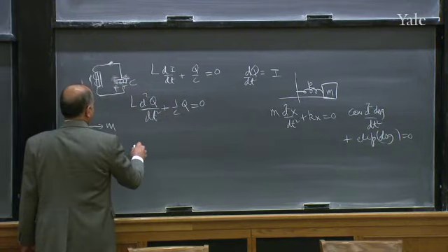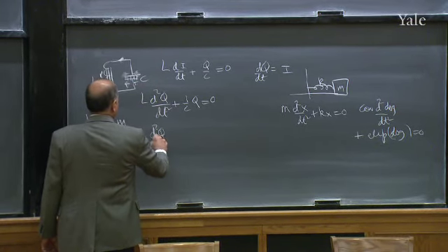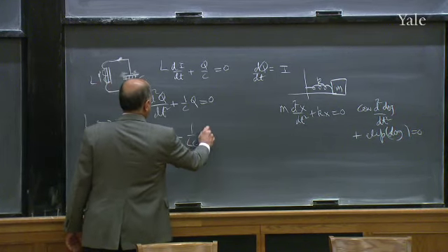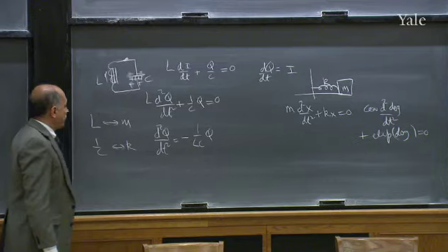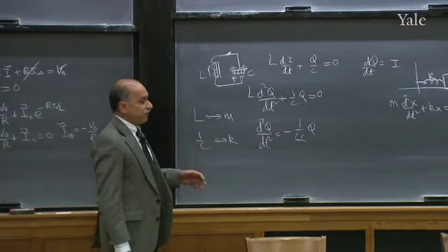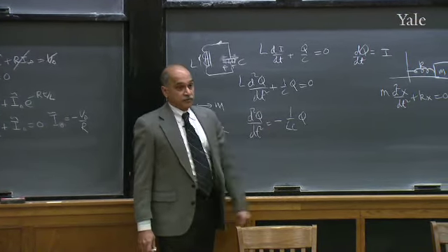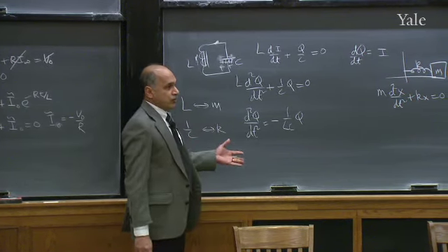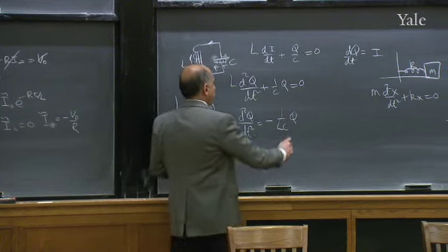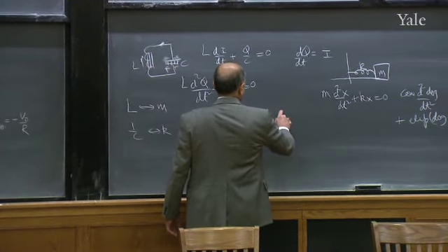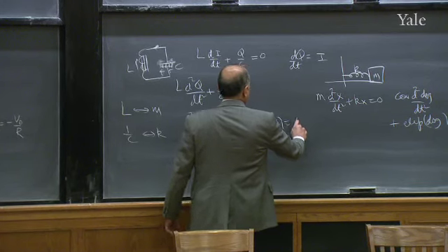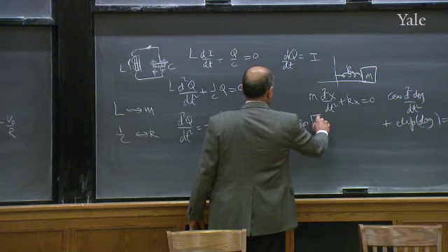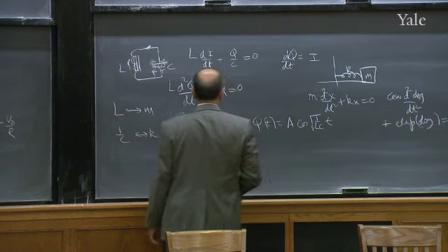So what's the answer to this one? Once again, it's a differential equation. You write d2q/dt squared is minus 1 over LC times q, and you're asking yourself, give me a function which, when I differentiate twice, looks like itself. There's always the exponential. There's also sines and cosines, and you can take any combination you like. One acceptable solution is some constant A times cosine of the square root of 1 over LC times t.